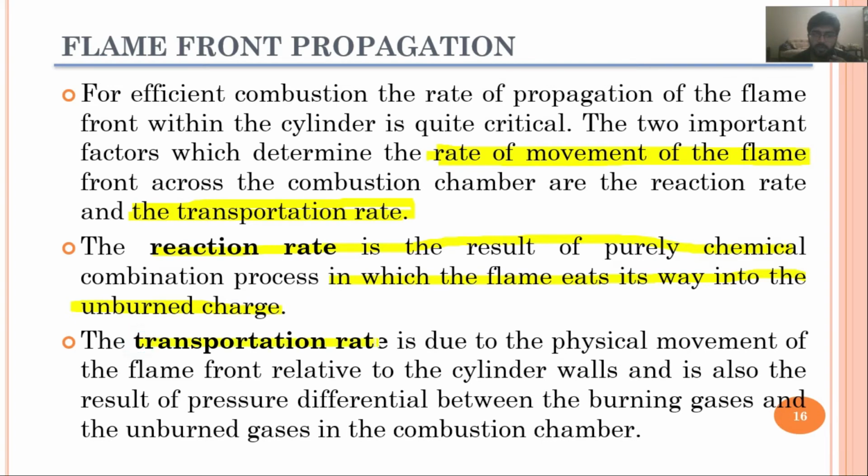whereas the transportation rate is due to the physical movement of the flame front relative to the combustion chamber walls, and is also because of the pressure difference as well. And these already burned gases are diffusing throughout the unburned gases and will force them to combust as well.